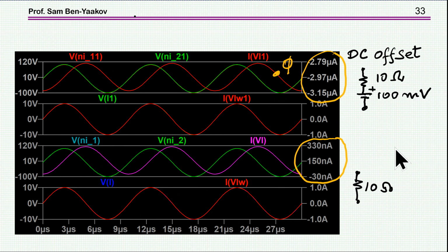And finally, I'm showing here what happens if we have some DC. Now, DC obviously is not transferred through the transformer, because you need a change in flux in order to move power from one side to another. So it is just affecting the winding that sees this DC. In this particular case, I have connected it to the output, and what it's causing is a shift in the flux.